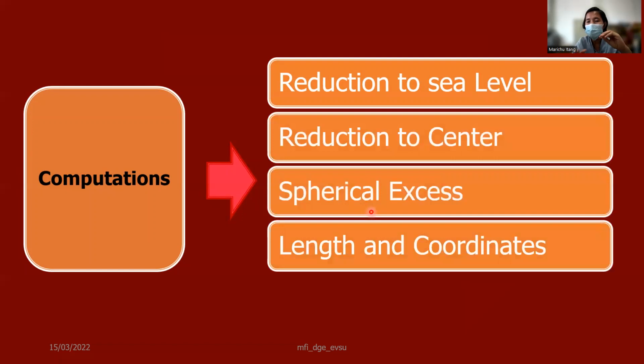After we determine the distance and angle of our network, we are going to assign coordinates to each corner of our stations. Since our control points have coordinates, we cannot put only bearing and distance as information on our controls. So we need to assign coordinates to our control.